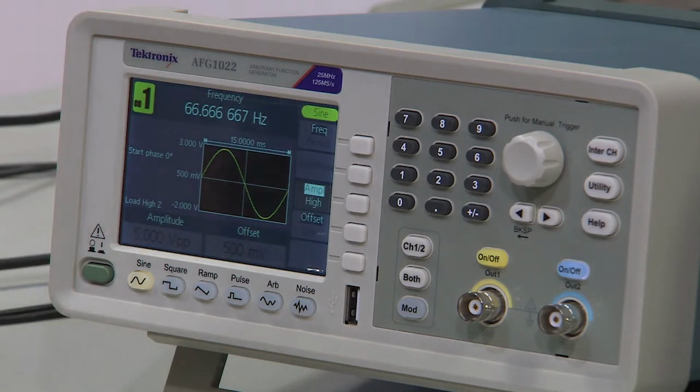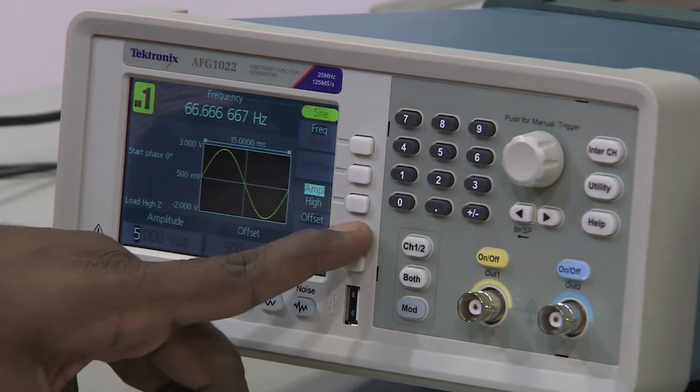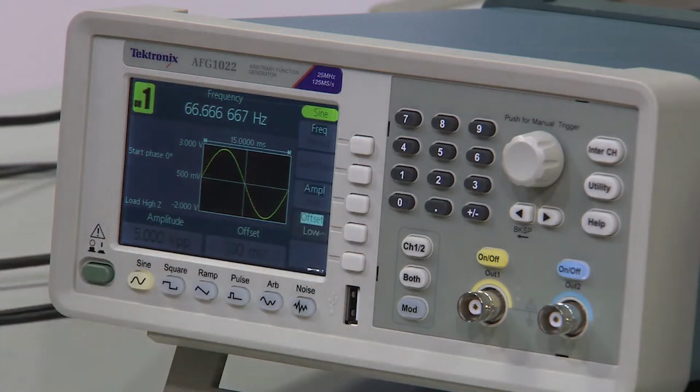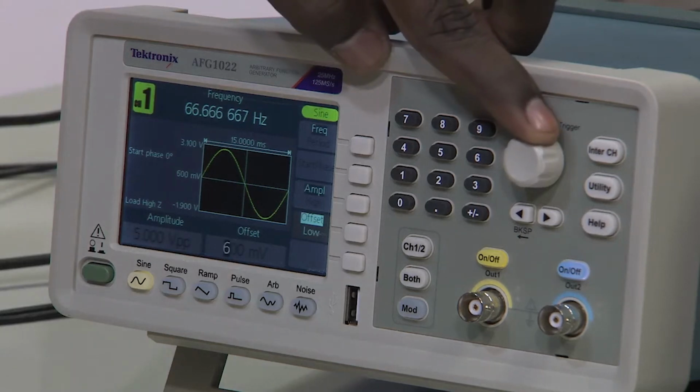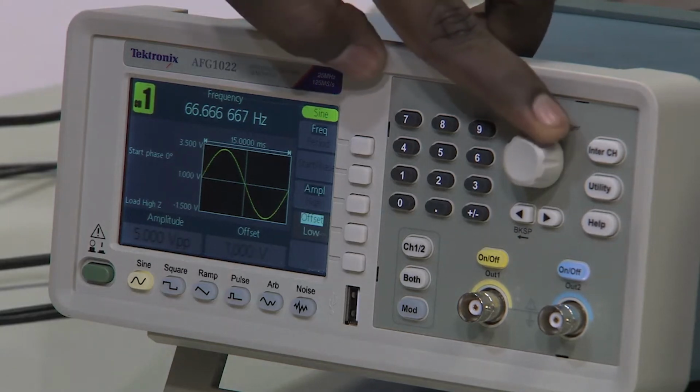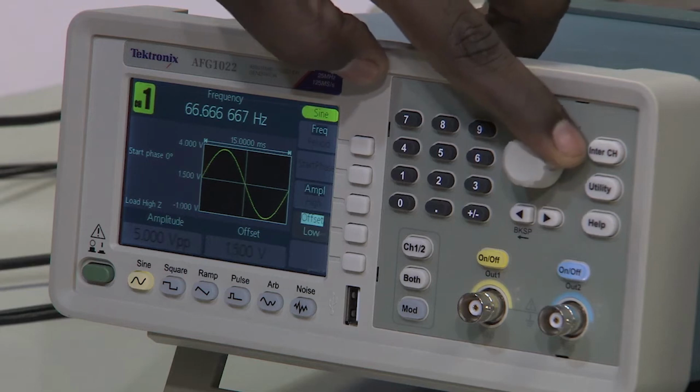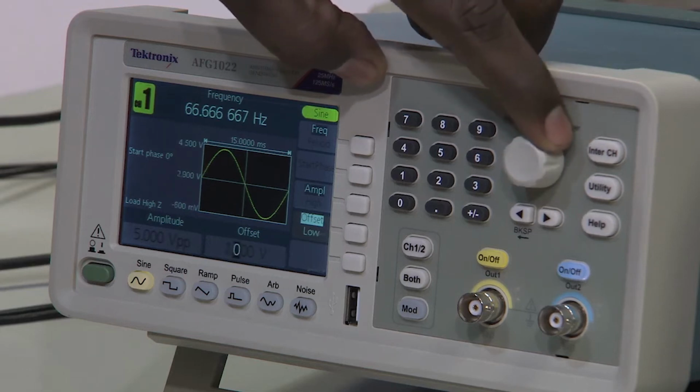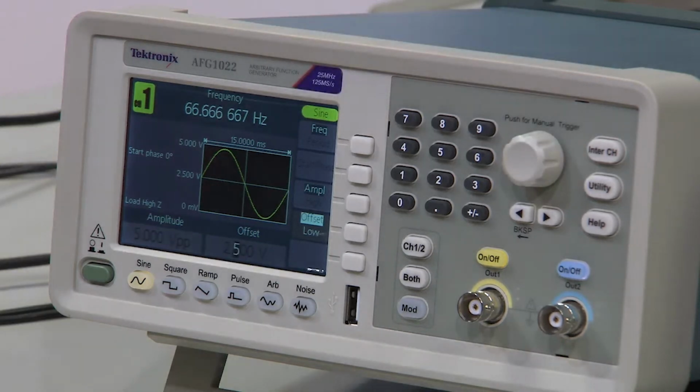Next one please. So, on the next white button, if you want to create an offset, you can create an offset by again changing the manual trigger or by using the display key or the other push buttons. Alright. So, if you see again the offset, you can clearly change the offset. Earlier it was minus 2 volts to 3 volts, now it is 0 to 5 volts, you see it is 5 volts only, but now it is from 0 to 5 volts. So, we can change the offset. Alright, what is the next one please?